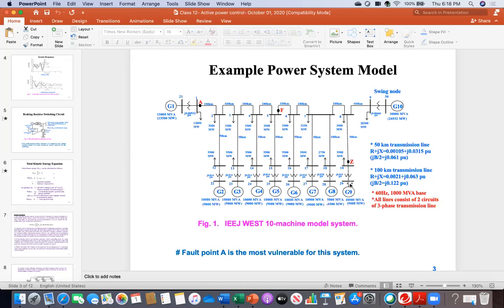Also, you will check that they have the same frequency. For example, this is 60 hertz. Now, if you connect a 50 hertz generator, that will also cause a problem. Again, both generators might heat up because there will be some circulating current flow. Also, their phase sequence must be the same. Phase sequence means ABC. The new generator should also have the same phase sequence, ABC.